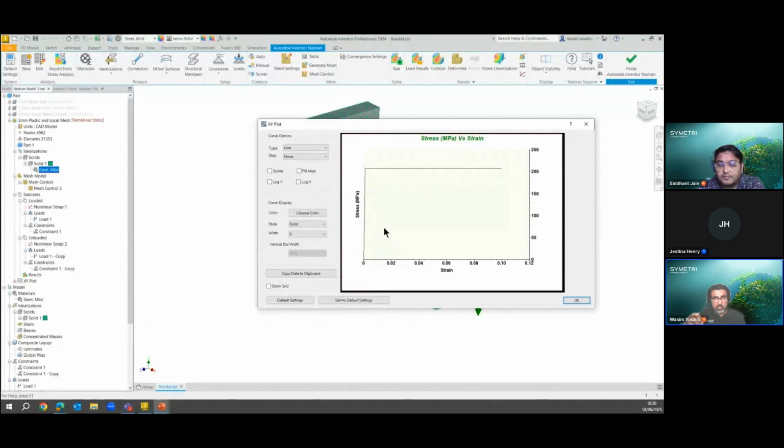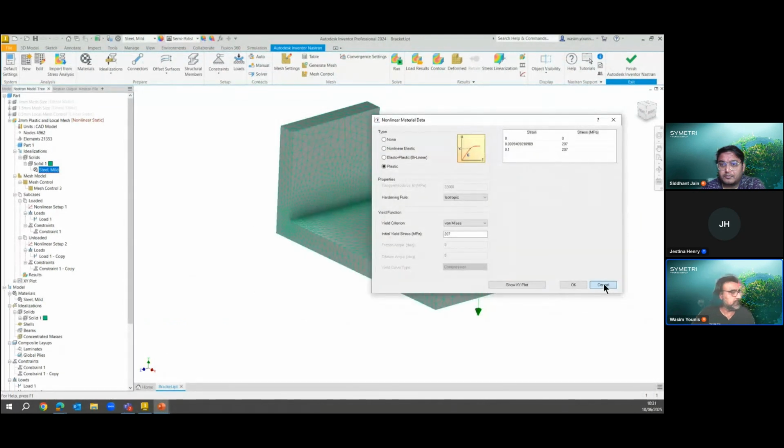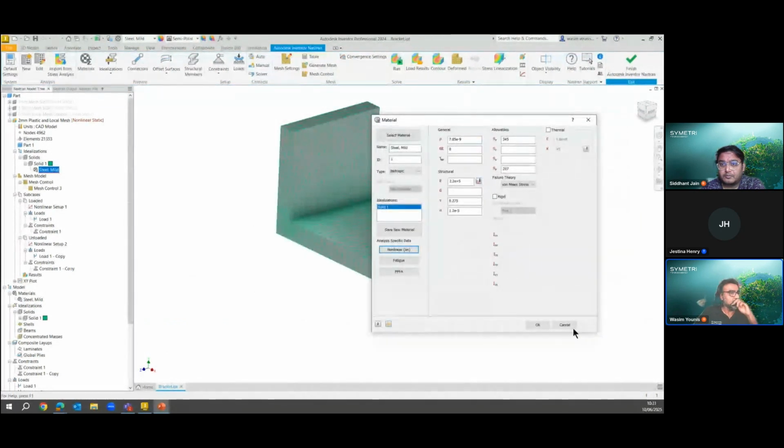it does not look at the corner values or the corner data. It always looks at the centroidal data. So when you think, well, it's not given, if the stress value is not going to be higher than the yield in the centroidal, even though in the corner it is, then you're not going to get any strain. So if you want to look at the results, to see something happening, look at the centroidal. That's the only thing I've changed, or one of the things I've changed.